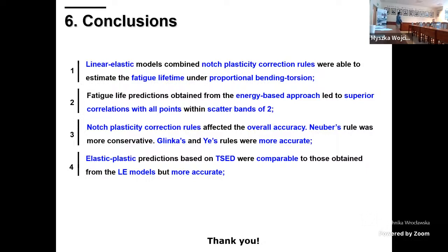Honestly, I think these methods are not a good solution for composite materials because the behavior is much more complex. I tested successfully the energy approach for composites to estimate the fatigue lifetime, but only under uniaxial loading conditions. Under multi-axial, probably it will be possible, but it will not be easy to create a methodology to assess and to reduce the multi-axial stress state into an equivalent uniaxial one. I think it will be complex, but we can try.